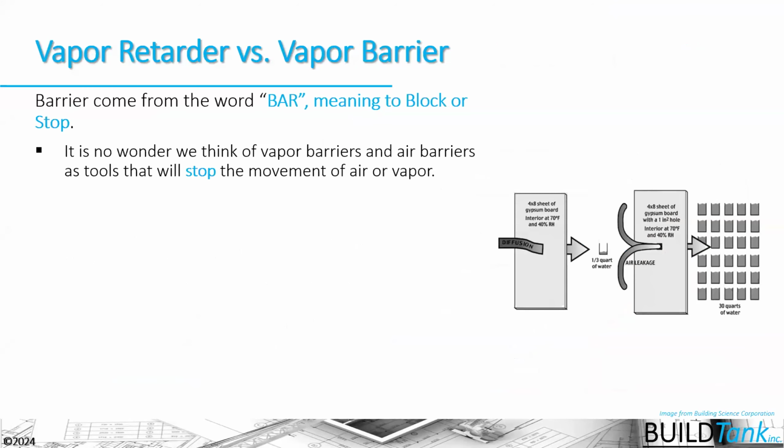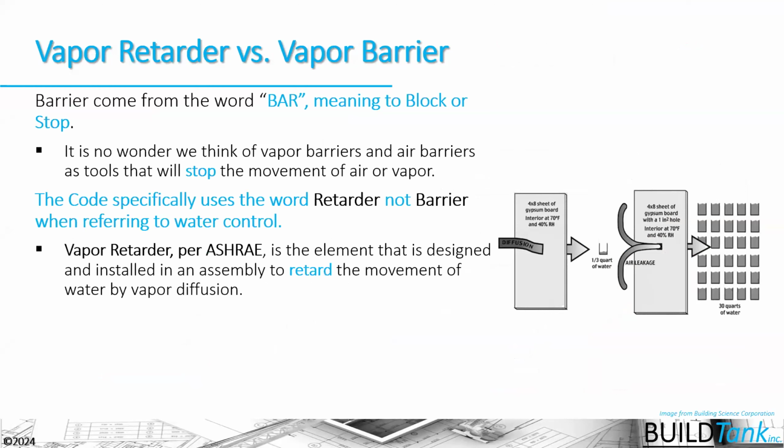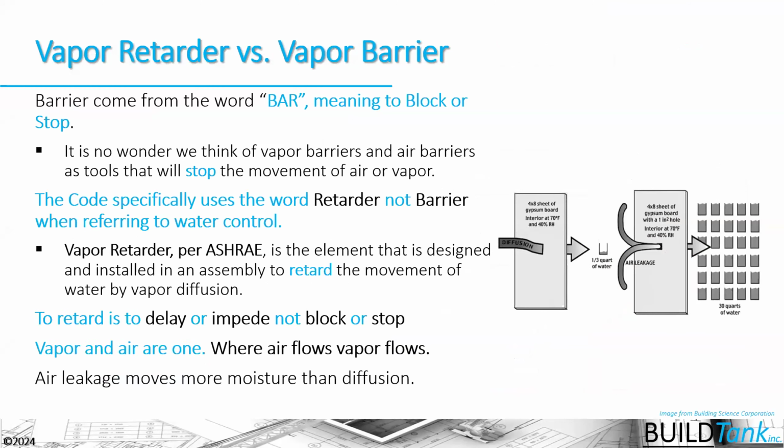which means that you need to pay particular attention to the next session that's going to be talking about vapor retarders and understand the difference between vapor retarders and air barriers. Unfortunately, we just don't have enough time to go into that in any depth, except to say that a lot more moisture moves with air than it does by vapor diffusion. And therefore, we need to really concentrate on those air barriers, not only from the perspective of maintaining that stagnant pocket of air and the integrity of our building thermal control layer, but also from a vapor control perspective as well.